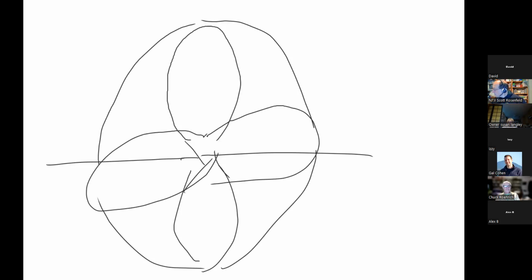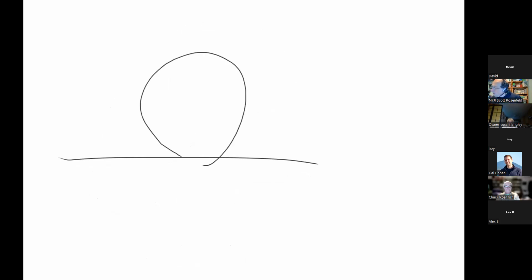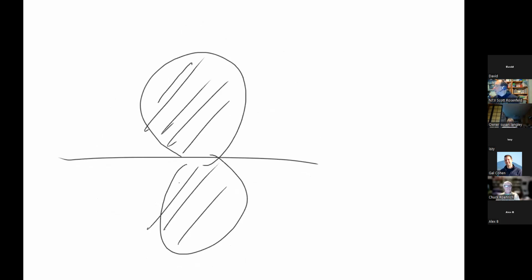Wouldn't the magnetic field be oriented differently if you twist it? Yes, but the electric field is what determines the polarization. And actually the magnetic field wouldn't make any difference because the electric field is the same. Basically, the magnetic field is kind of like around in a circle. So the radiation pattern of a dipole, if we look just at it from the side, it would look like we cut into a donut. And the donut would be like this, and the donut would be like this.